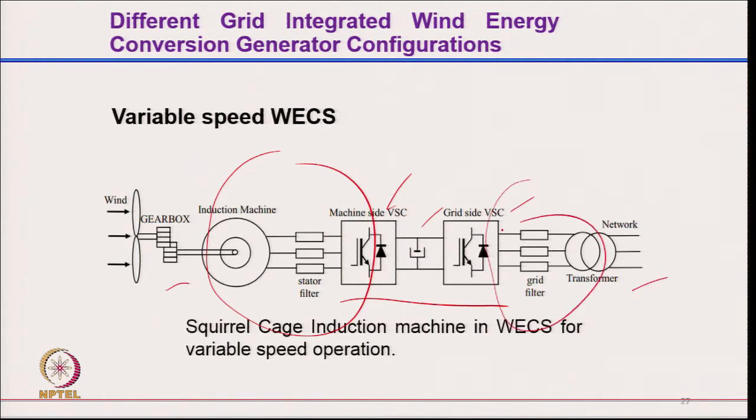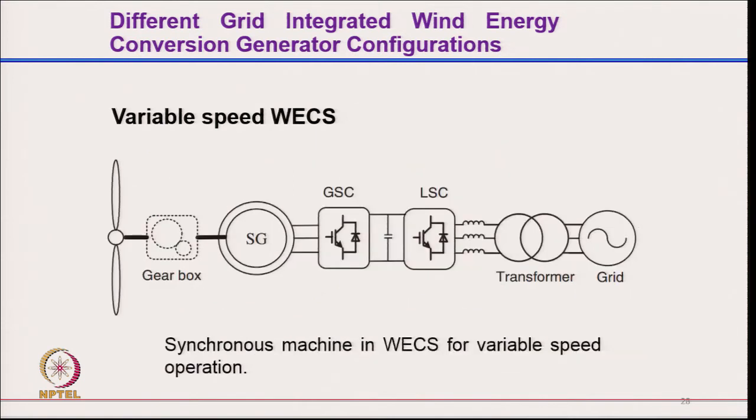So, here it is more important that we worry that this power is fed without power quality problems, even though there may be a power quality problem in the grid. So, why are we using this converter at more than twice the rating of the power which you are generating, because it is processed twice? Since wind power generation is able to generate around 50% energy from the wind blowing by putting in a maximum power tracking algorithm, that is the reason we are able to process the power with a couple of power converters, the whole power.